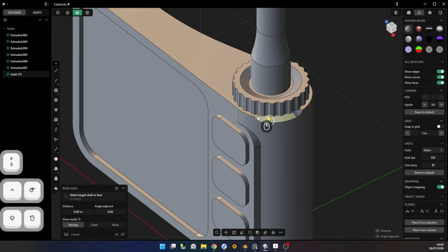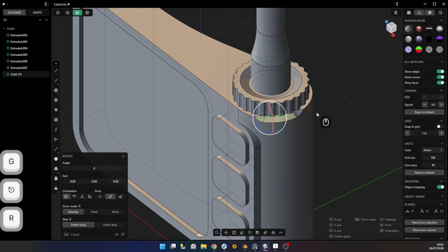We can actually edit it, but it's gonna be a bit tricky. So we could rotate it and it could rebuild itself if we move precisely around the center axis. So I'm gonna go X-ray mode or Alt Z, press rotate, and then set the pivot in the middle of any of those axes.